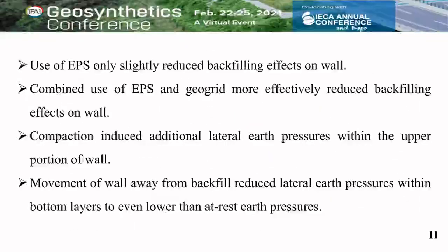Conclusion. Use of EPS only slightly reduced backfilling effects on the wall. Combined use of EPS and geogrid more effectively reduced backfilling effects on the wall. Compaction induced additional lateral stresses within the upper portion of the wall. Movement of the wall away from the backfill reduced lateral stresses within the bottom layers to even lower than at-rest stresses.